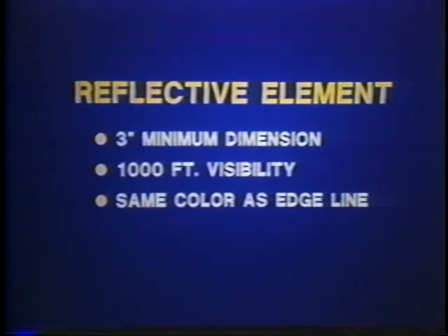Post-mounted delineators are another positive guidance delineation device. No matter which of the variety of post-mounted delineators is used, it must meet the requirements you see here. Reflective sheeting dots and strips can be used to satisfy the basic requirements. The MUTCD states that the delineator color shall conform to the edge line color. So, if the delineator is adjacent to a yellow edge line, it would be amber. Right-side mounted delineators are always crystal.